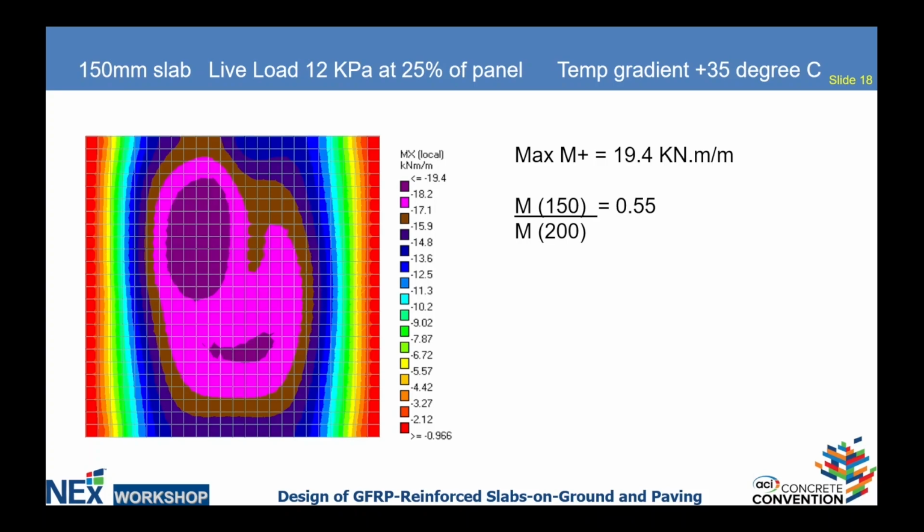So this is telling us that it's not the stiffer, the better. In fact, if the slab is more flexible, it can conform to the ground better. If the ground needs to deform, you would have a better design if the slab is capable of elastically deforming and conforming to the deformation of the ground.